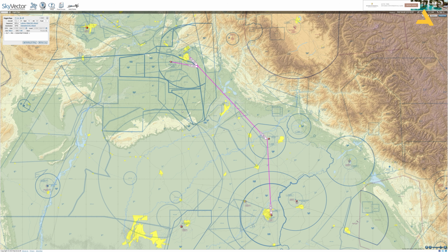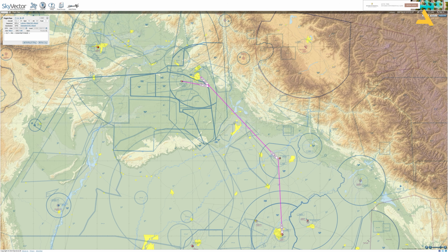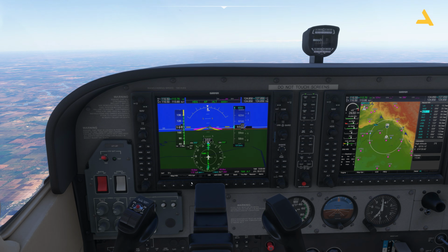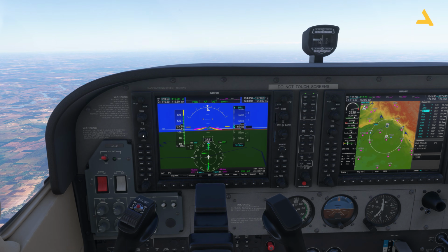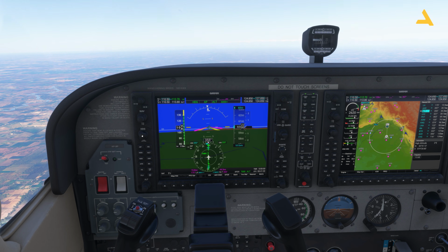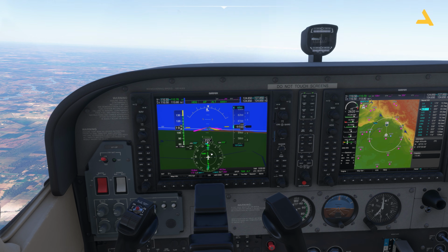Let's say they say fly towards this VOR inbound radial 175. So when they say inbound radial 175, fly towards the VOR, it means you have to set your heading to 355 for outbound. Interesting. So that's really interesting. Now almost half the way, I will just adjust the course a bit. Sorry, I have to go to the left side because I'm still deviated from the path.